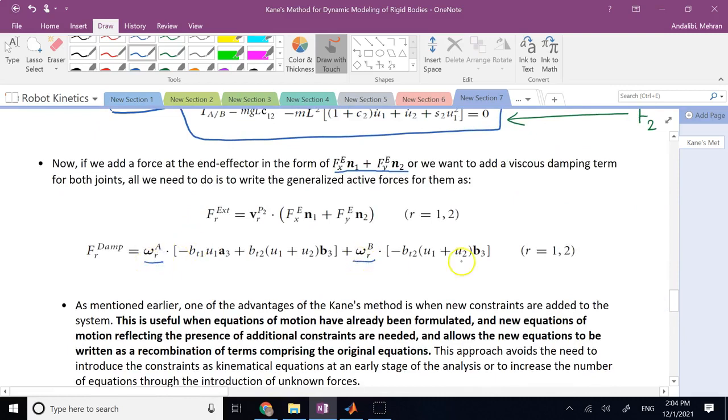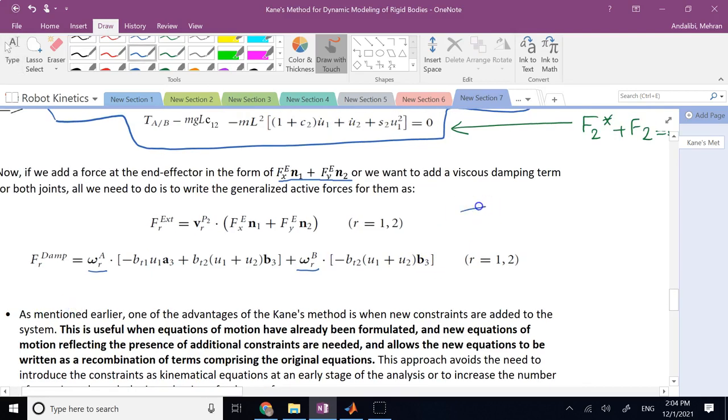Now, what are they? Let's say what is the second viscous friction at the joint? Well, if you remember, viscous friction is what? The viscous friction at the joint is formulated by T equals some coefficient B times the angular velocity at that joint, Q dot.